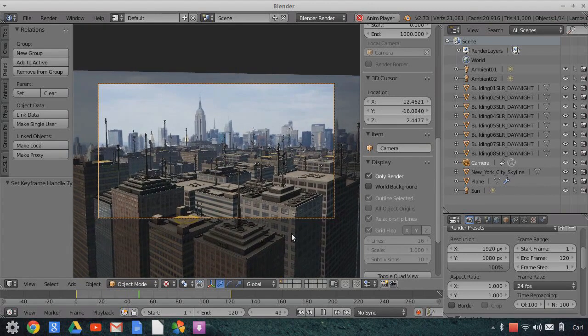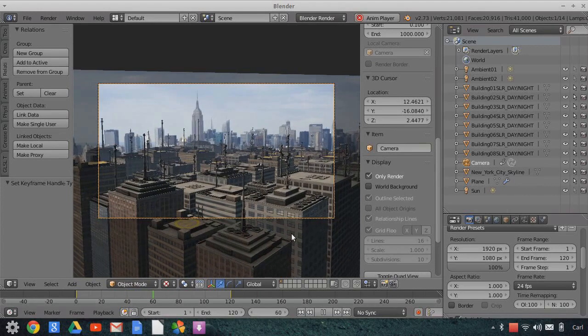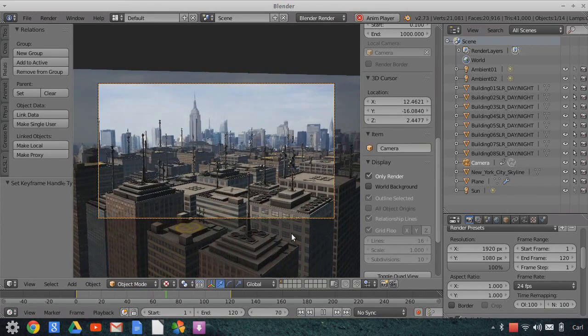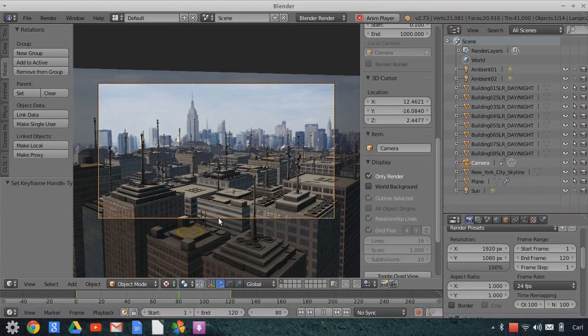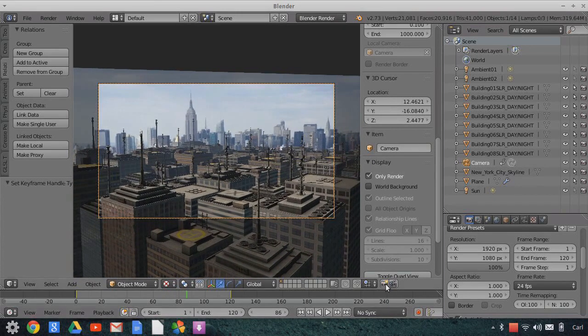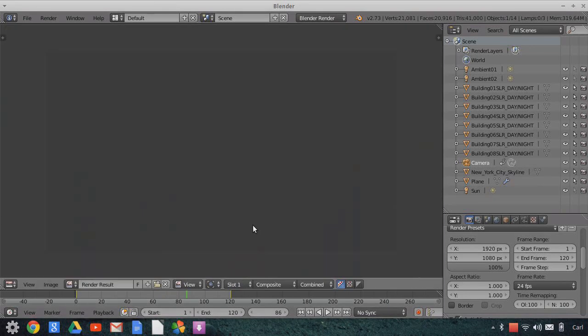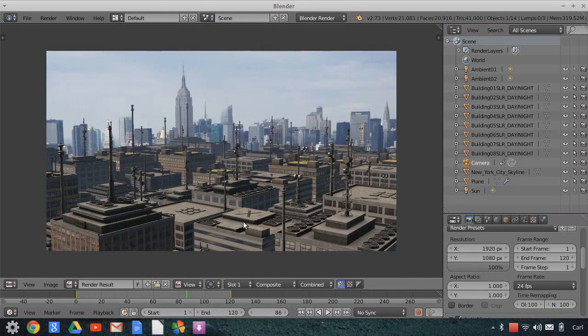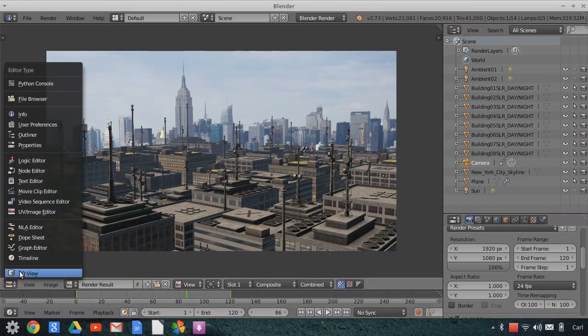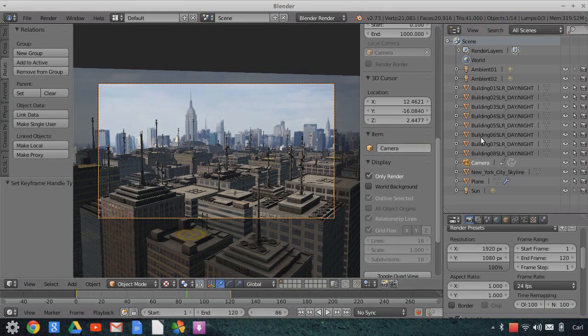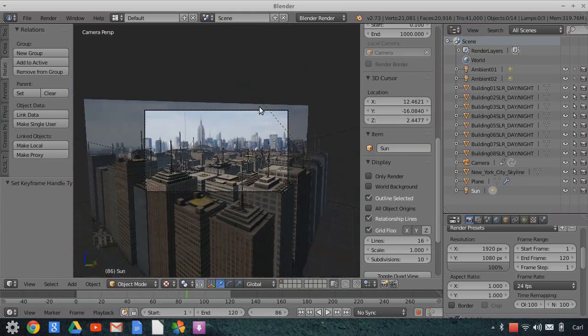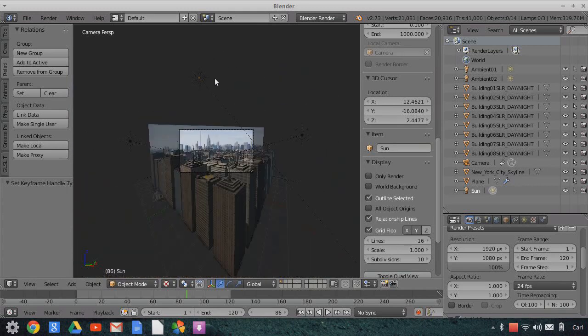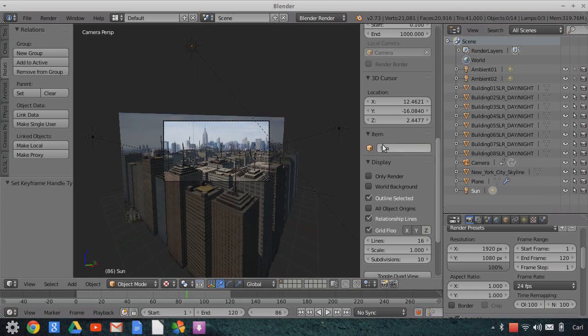Now, one trick you can do is if you take all of the textures from the pack and unpack them, you can alter them in a photo editor and reduce them perhaps by 50%, and that would increase your preview time if the resolution of the textures was half of what it is now. And with the objects at the distance they are from the camera, I don't think that it would be quite as noticeable. You could probably get away with half resolution in that situation. But otherwise, I think it certainly moves efficiently and quickly enough.